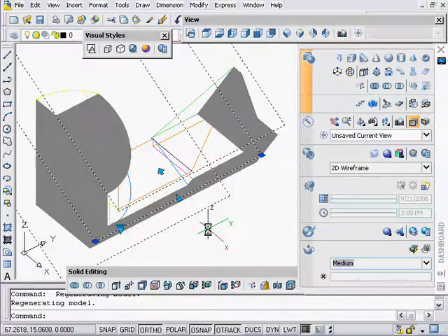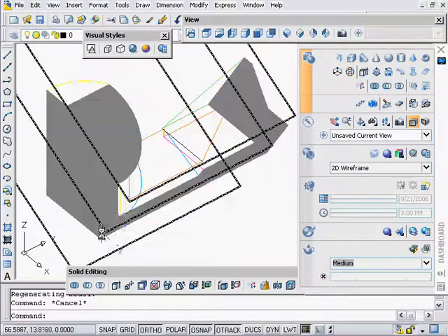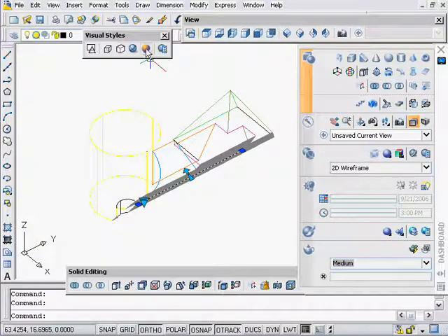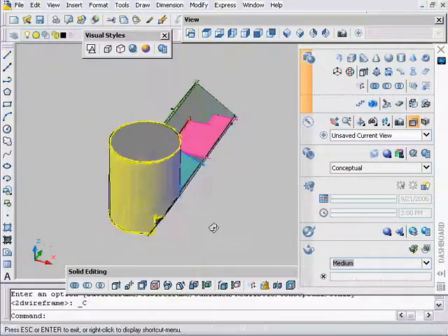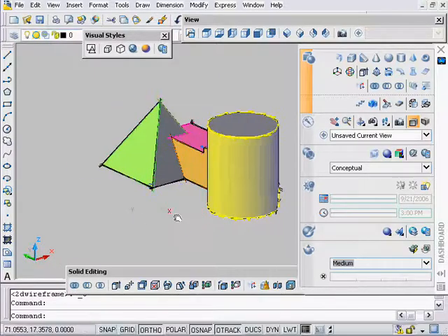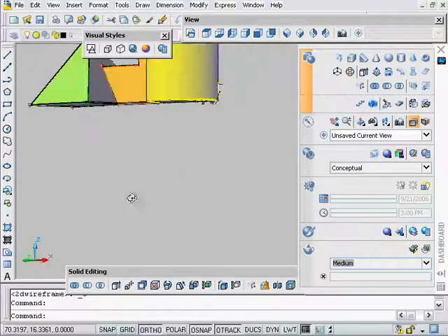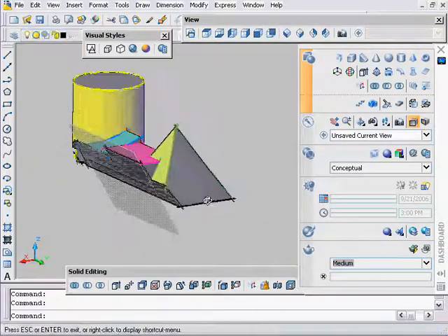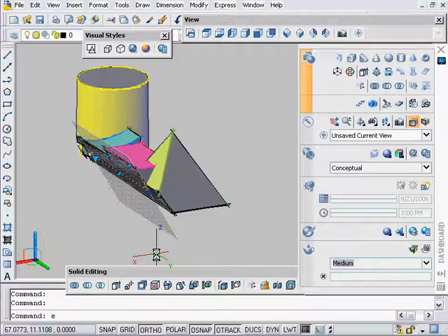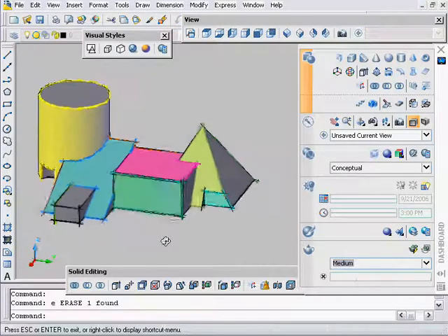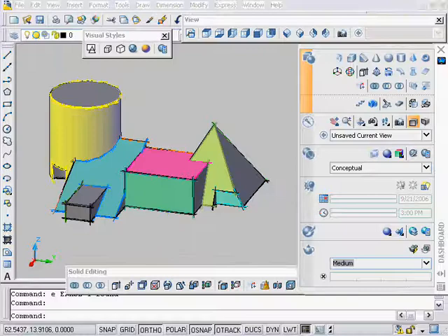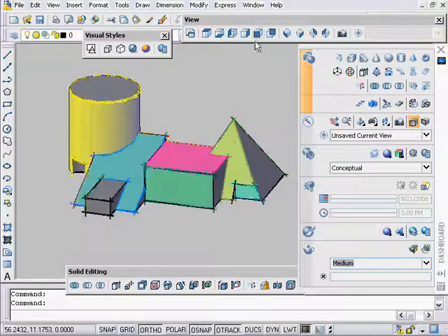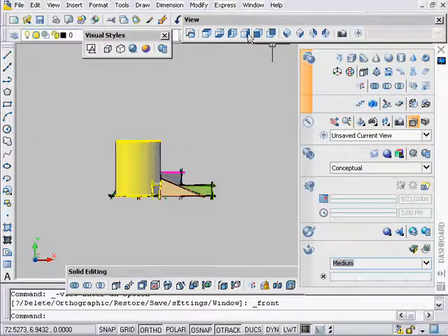3D aspect where you can squeeze it down this way as well. Just insane how many settings we have on here. And back to section plane, okay. My conceptual view, spin that around with my objects where I just used my colored faces. Shift middle mouse. And then again, the nice thing is you erase it and everything comes back just the way you had it. So really that's it. It's not that complicated.